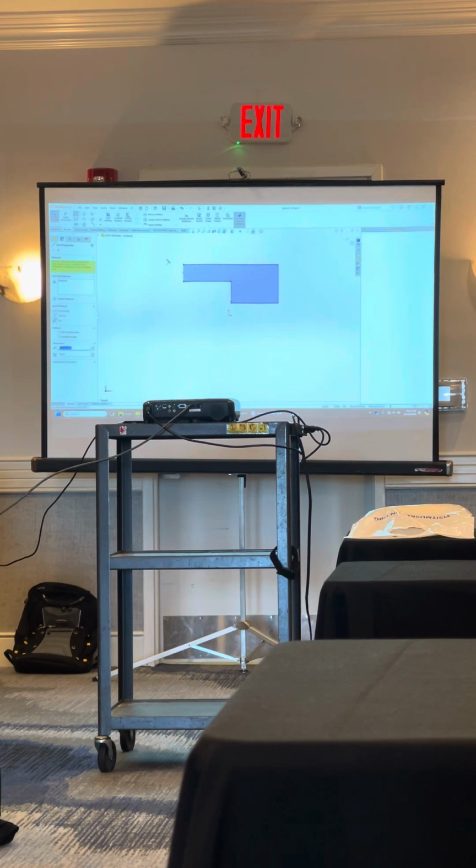Make sense? The other methodology is what we call click-drag. It means I push the button down, leave it down, stretch the line to wherever I need it, and let go, and you won't get the rubber band effect. You still get the line command, but now you can draw a couple of parallel lines or perpendicular lines or whatever you need at that time. Kind of cool? So stay away from the right-click cancel, the escape cancel, or anything like that. If you find yourself restarting that command, just remember click-click versus click-drag. Good deal?